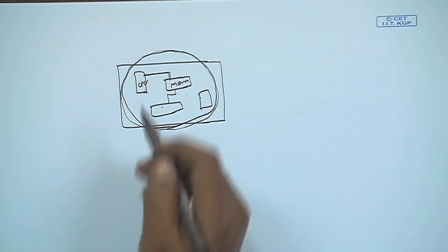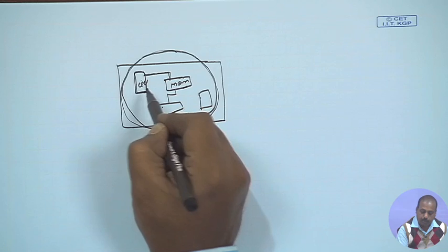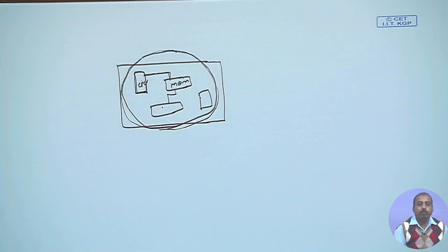Now, that is not the situation here. Why? Because even if everything is fine about this particular design, maybe the silicon itself may be impure at that point. So, that way some fault may develop. So, since I am designing the whole chip myself, the testing responsibility also comes. So, I cannot say that these individual components are fine and I need to test only interconnects. So, here the complexity is more, I have to test the chips, the components as well as the interconnects.